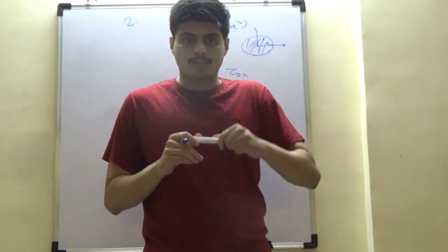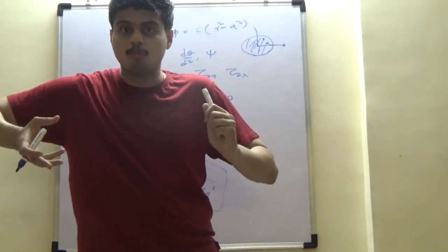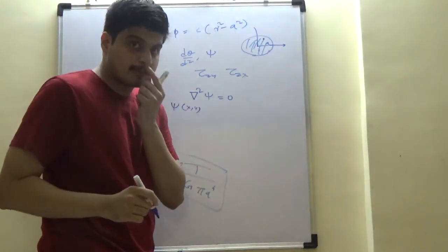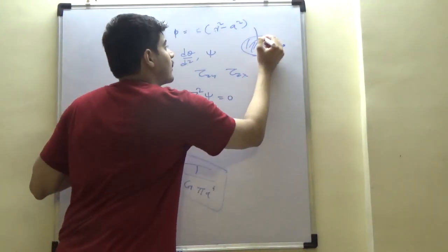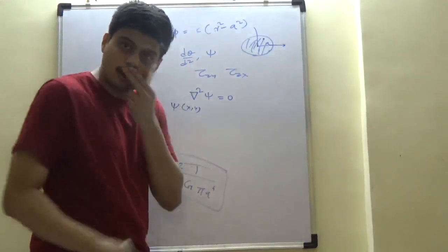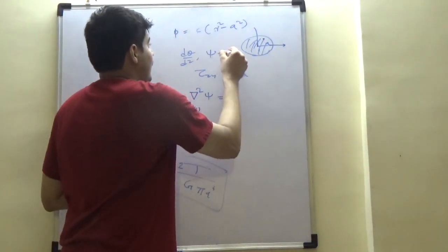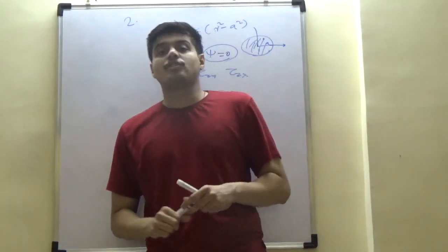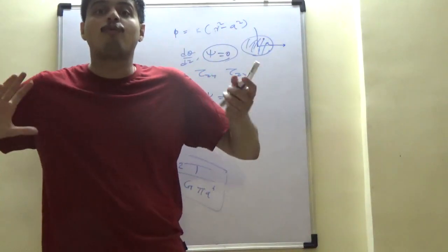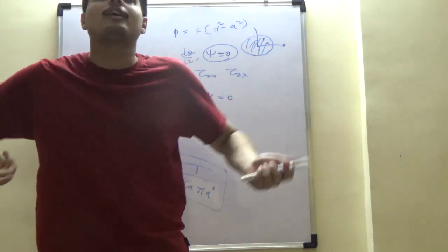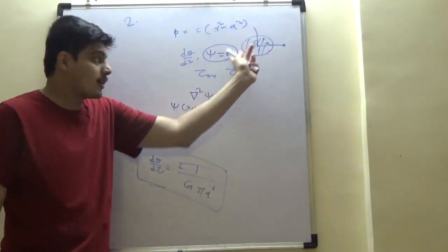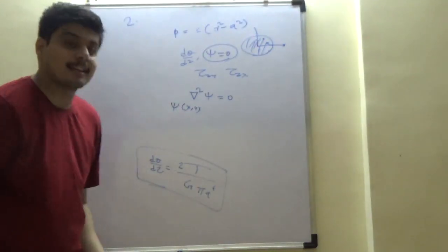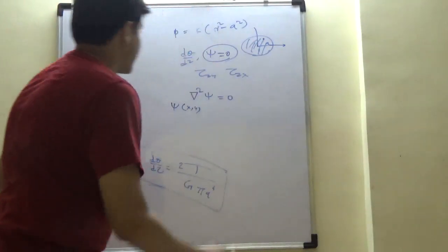For a solid cross section, when this disk is going to move, if I just shift my coordinate frame, w would change. But a circle is doubly symmetric, so just by changing the frame it should not change. Which means psi has to be 0 everywhere. Circular cross sections of solid nature have no warping. They have pure twist. The rods have no warping but pure twist, and that is an extremely important answer.